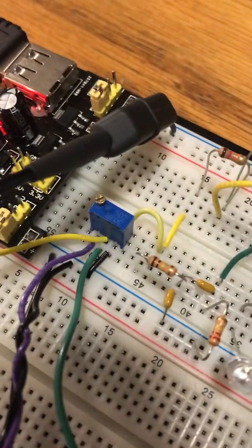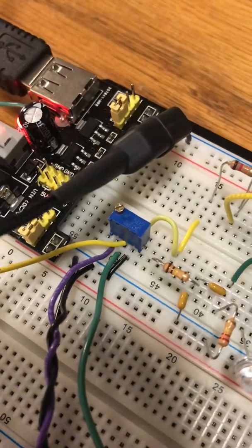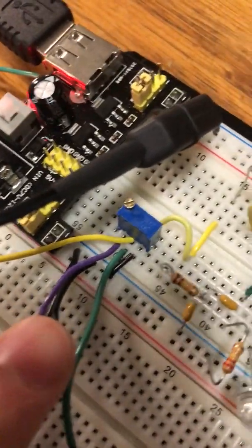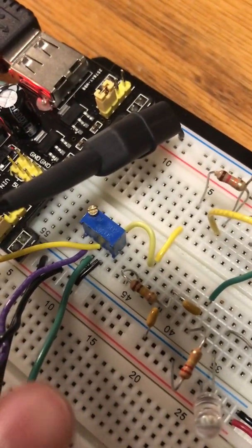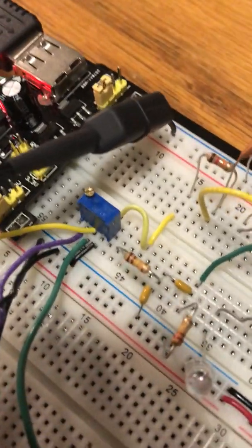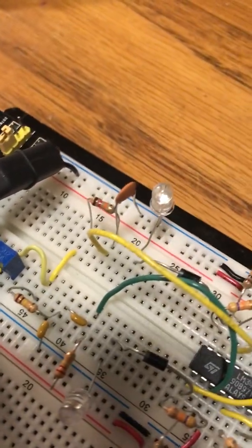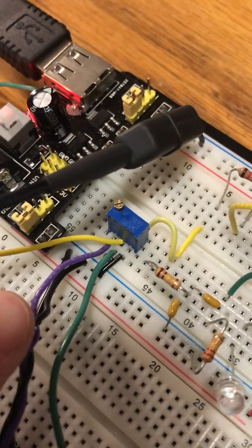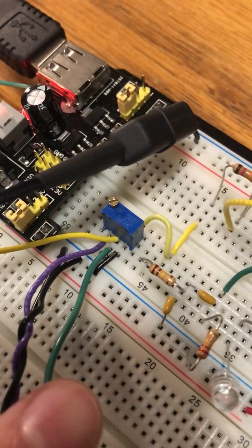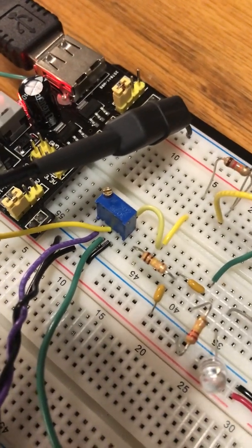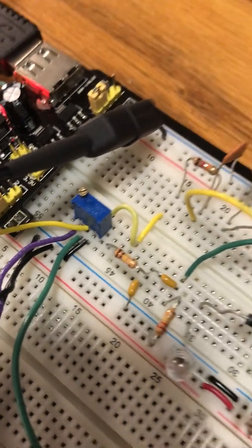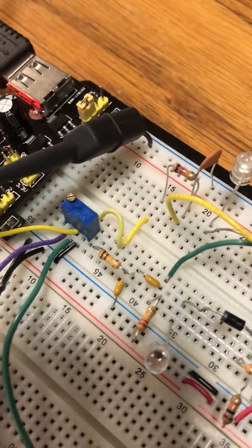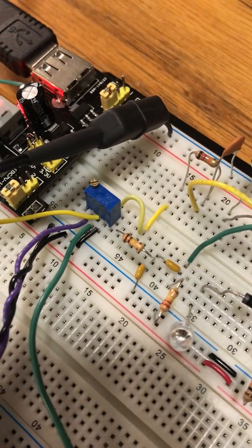So this is our voltage divider. The purple wire is the input, and the green wire is the output. We can tweak this potentiometer to reduce the voltage to whatever we want. Right now we're doing a 5-volt amplitude input for the purple wire, and the voltage divider changes it into a 1-volt amplitude output for the green wire. By the way, this yellow wire is also an output. The input is an AC network sweep, by the way.